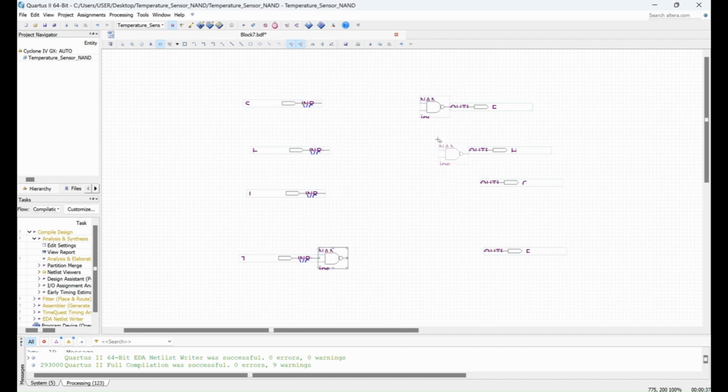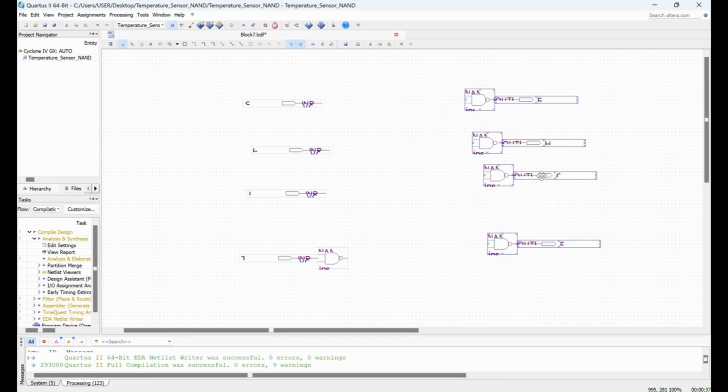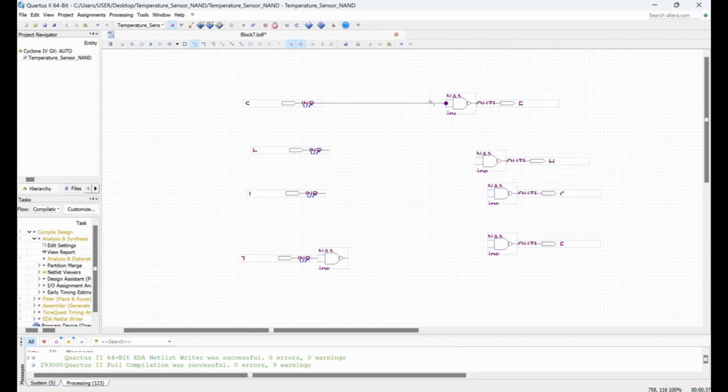In this part, we'll be using 5 2-input NAND gates, 2 3-input NAND gates, and 1 4-input NAND gate. And we just connect them respectively to our desired inputs. So for the R output, it's just going to be a NOT gate, and in the universal gates, we just be using a 2-input NAND gate. We put 3-input NAND gates and also a 4-input NAND gate so that it can replicate the same output as using only one AND gate, because we're using only universal gates in this circuit.